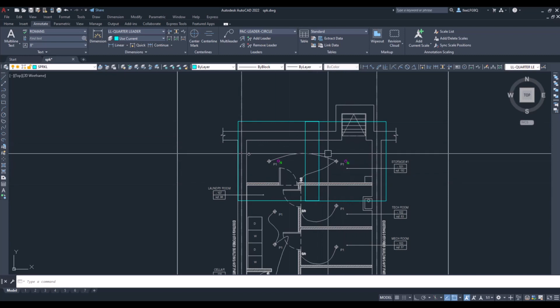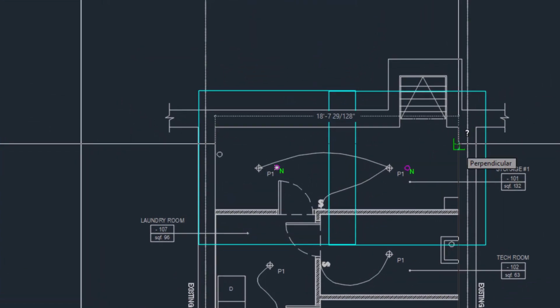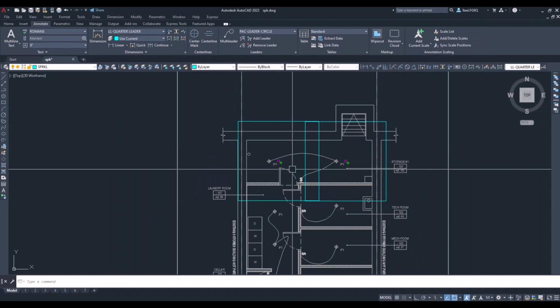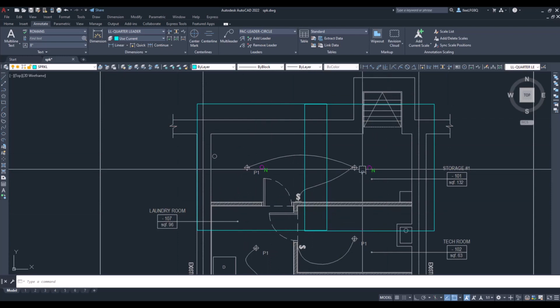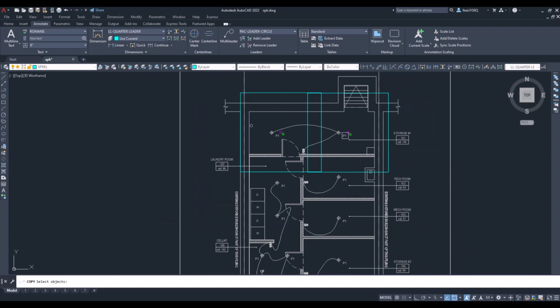If we had one sprinkler head, we wouldn't be able to get the coverage for the whole space, right? Because the distance here to here is more than 12. So in that case, we would need 2 heads. And you want to keep some sort of alignment with the lights, which we did, and also some sort of symmetry. Okay, so now we're going to lay it out for all the other spaces.